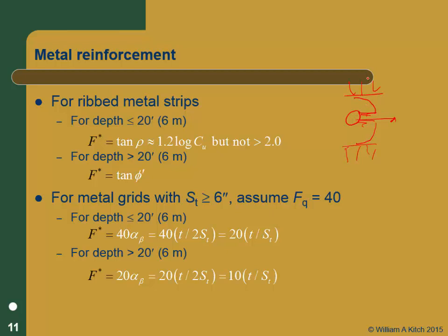The vertical stress here is going to increase the capacity up to some point. Once this failure surface is wrapping around itself, there's a limit to how much you confine it. You're not going to get any additional capacity from the confining stress.